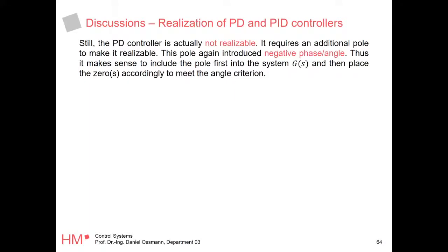So what happens when we add a parasitic delay? We add a pole in our system, and that pole again gives us some negative angle. So what will happen is, no matter where we place that pole, it's gonna drag our root locus curve away from that point A, right?